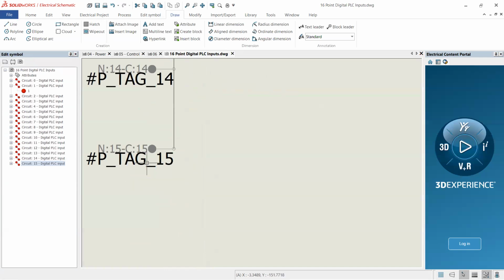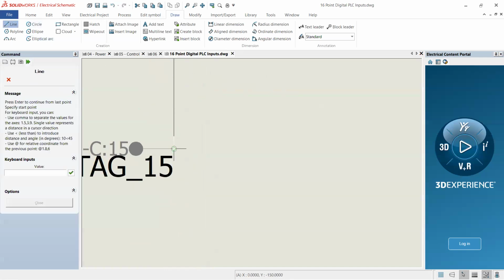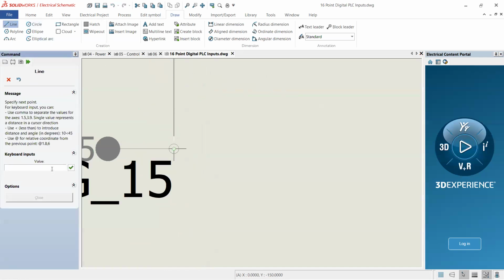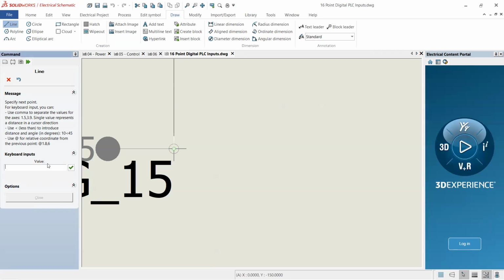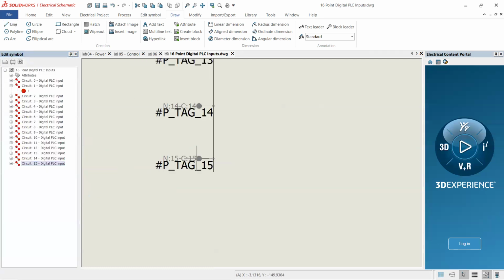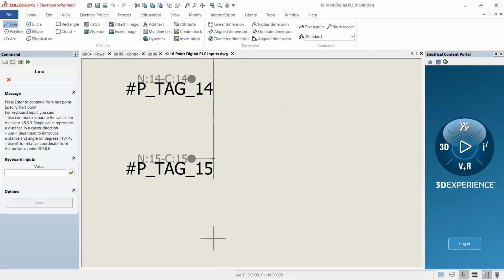And I'm going to do the same thing exactly at the bottom, except remember, negative, right? 0, comma, negative 2.5. Oops. Oh, and I screwed it up. Remember relative coordinates. Line. Relative. At 0, comma, negative 2.5. There we go. And then, it's really just a matter of closing in the box. So we're sort of done.